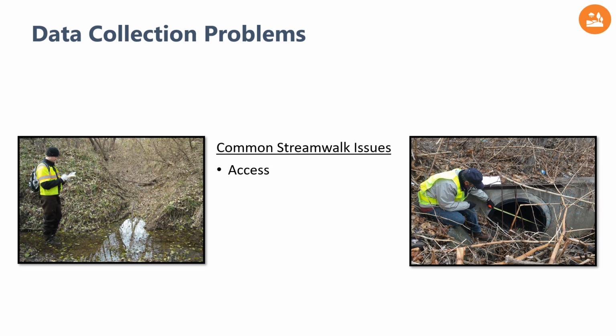It's really hard to get good data when stream walks are restricted by brushy areas, private property, road hazards, and dangerous terrain. Time is another factor. Stream walks can take months to complete, due to resource constraints, training requirements, and weather factors. River characteristics can make stream walks less effective too. For example, bank conditions can be difficult to document on wider streams,